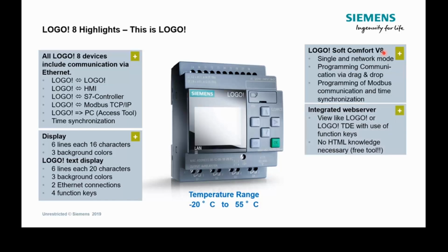We've got the integrated web server, so it comes in 2 styles. There's a standard web server, which is our Siemens branded web server. It has 2 pages, one that looks like the front of the LOGO!, so you can push all the messages through onto the web server as well, and also a page that looks like the LOGO! Text Display. There's then a further page which gives you free access into a table where you can put any address from within the LOGO!, and then you can monitor and modify that value as you wish. Maybe a good tool there for commissioning.